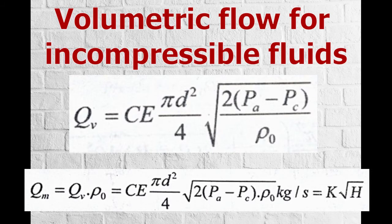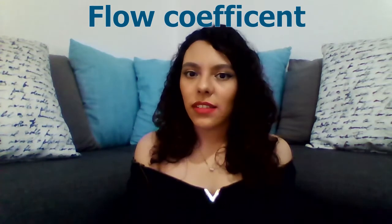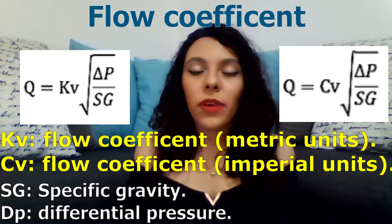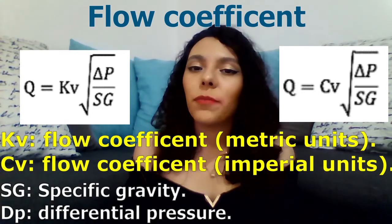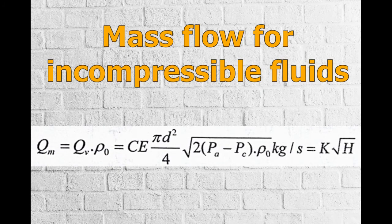This coefficient is dimensionless and practically constant for any diameter of the same model, so it's normally provided by the manufacturer. The flow can also be calculated with the flow coefficient, which is a design factor that relates the difference in height or pressure between the inlet and outlet of a flow restriction, and that depends on the Reynolds number, which I will explain to you at the end of this video. The higher the flow coefficient, the less pressure drop. On the other hand, the mass flow would be calculated with this formula.